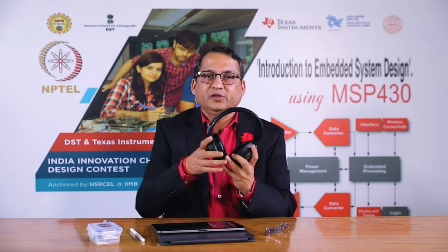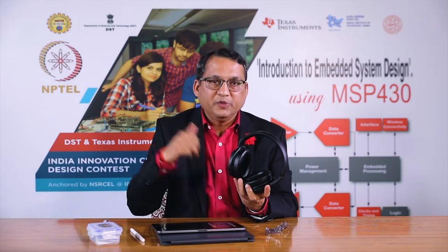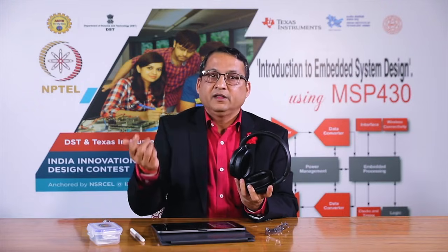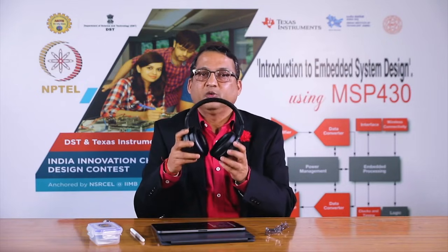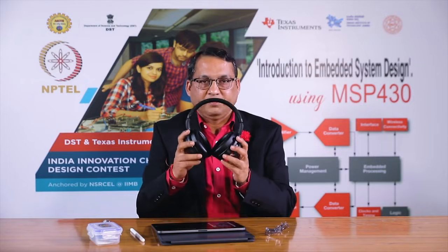produces an anti-phase version of that sound and mixes it into the speakers in these cups, so that you are actually hearing three sounds: the music that you are playing, the external sound that is leaking through the cups and entering your ears, and the anti-phase version that this headphone is creating. That anti-phase version cancels the noise which is coming from outside, and you hear only the music that you are playing. And so, it gives a great example of an embedded system.